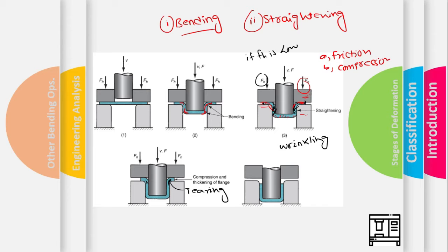The progressive downward motion of the punch results in continuation of the metal flow caused by the drawing compression. There is some thinning along the walls of the drawn cup during this process. As an empirical observation, when we perform the drawing operation, at least 25% thinning takes place, mostly near the base of the cup.